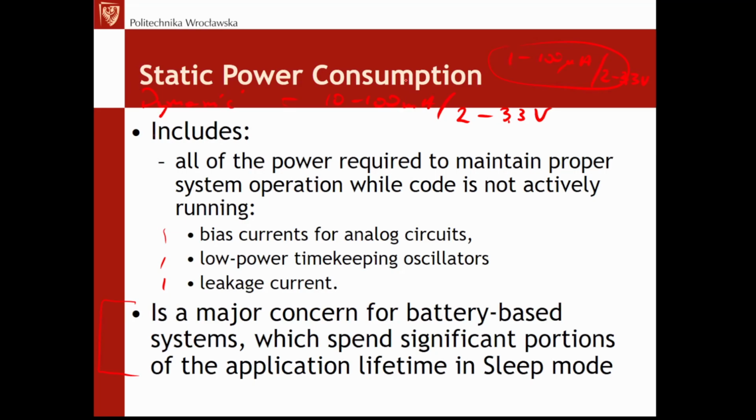In digital circuits, it's more or less something like this. The dynamic part is what we need to especially focus on if we construct a device that is running 100% of the time, or the majority of the time at full throttle, while the static power consumption is naturally important if we talk about battery-based systems, which are to be very frugal in power consumption, so that we need to squeeze the most out of a tiny battery.